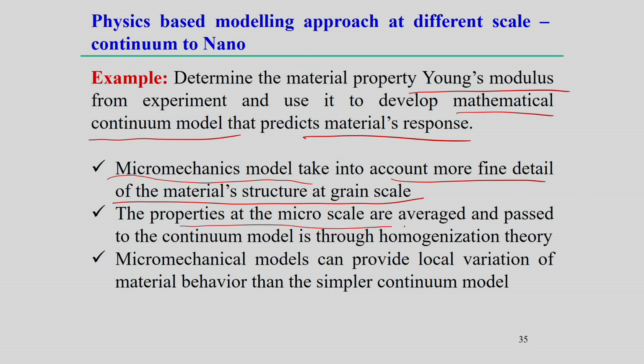So, as an example, if you measure the Young's modulus in the 110 direction for a single crystal structure, and the 111 direction and maybe other directions, then we will get a huge variation of the Young's modulus, because the crystal directions are different. So, for this variability, normally we do the averaging out, and we can give the average Young's modulus to the next scale to develop a particular model.